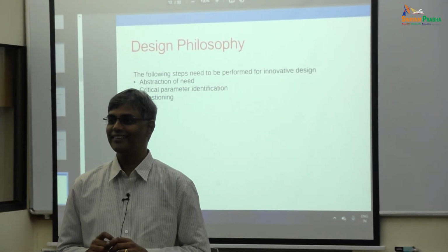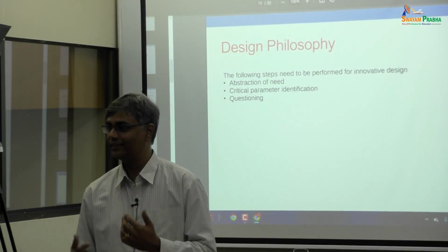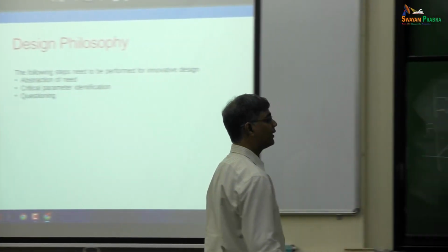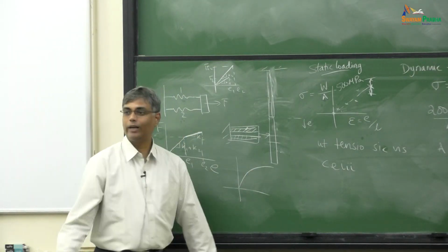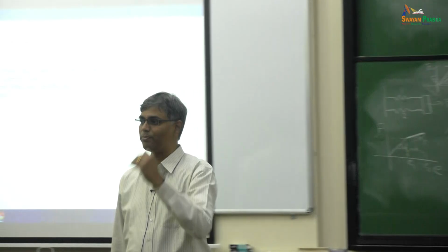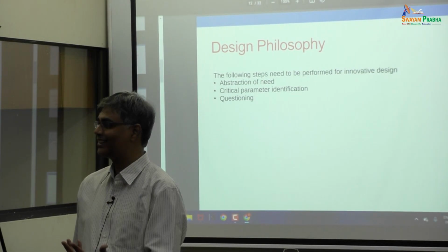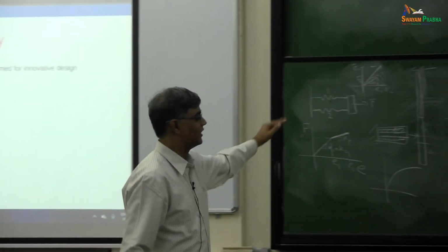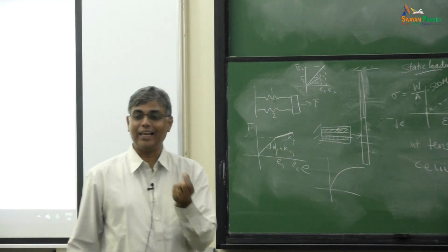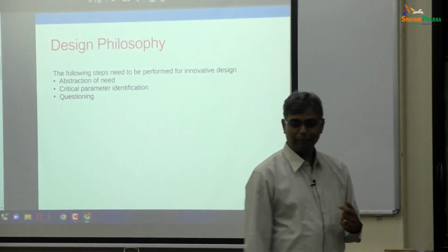Got it? So now imagine instead of just 2 springs, I have many springs. What will happen is I will get a real force displacement curve that will look like that. If I had many springs, 1000 springs, it will look like that. By the way, that is a much more realistic description of how materials behave than just this straight line. So by having straight line elements, we are now able to get a much more realistic description of how the material behaves. Yes.